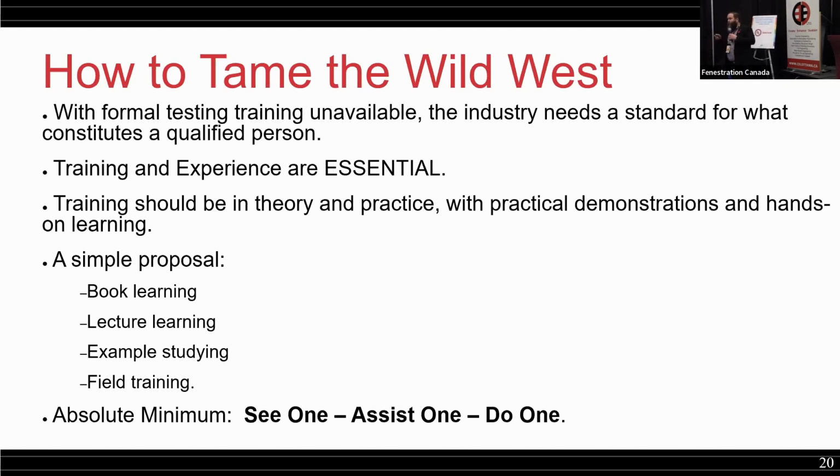Economy comes into the code. The code is a reasonable standard. I'm primarily a structural engineer. As a structural engineer, my code is designed such that 1 in 50,000 people in this country will die in a structural collapse, statistically. That's the basis of the code. 1 in 50,000 fatality in structural collapse.